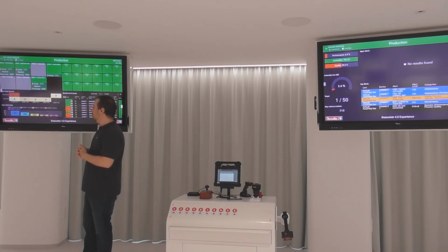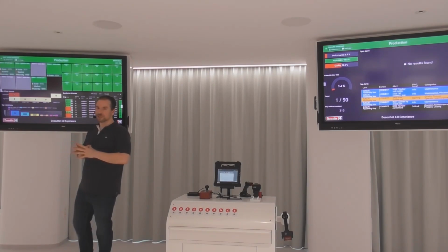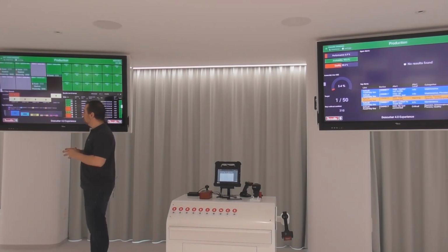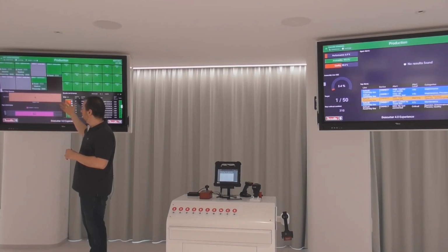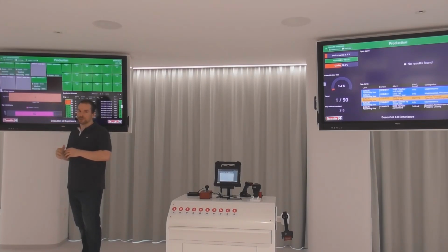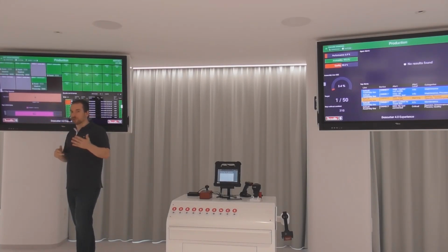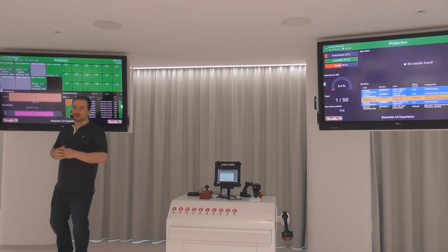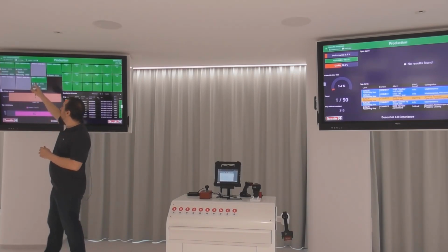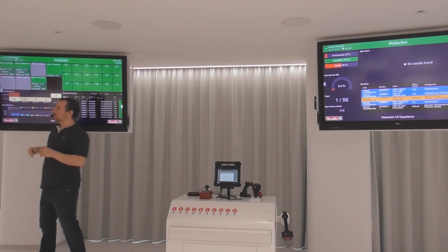Normally these statistics you can just have for one shift and have a look at the details. And below I see the tools with the highest not okay ratio, so I can have a look at the details. And I see that the operator on this station was releasing the trigger too soon. So obviously he just needs some training because it's causing me delays in my production.